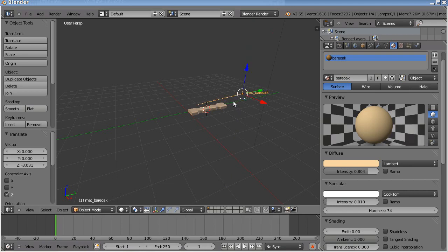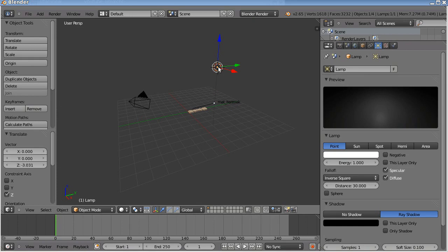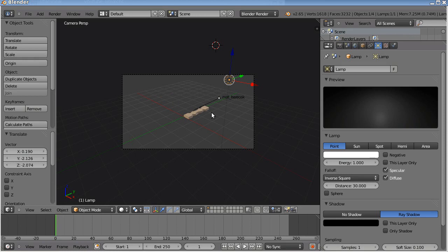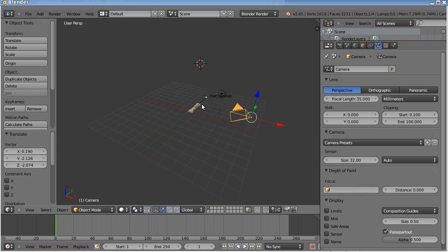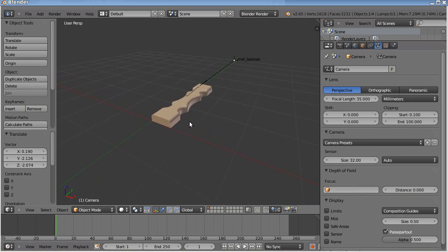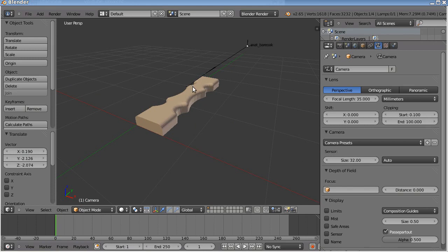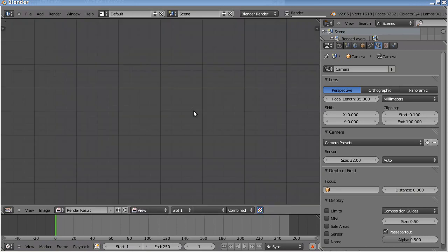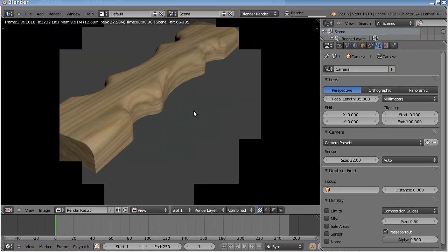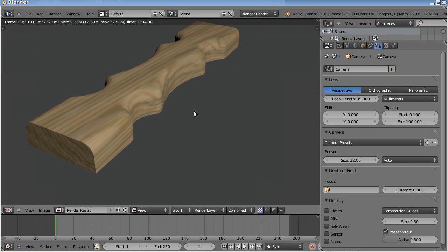Here do we have a light ball? Yes, we have a light ball. Grab it also down. Now move with 0 to see where the camera is. 7 is the top. I will move the camera a little more inside. I move in view, hit Control Alt 0, and we have the camera there where we would like it. And with F12 we will have a nice part, as you see here. This is basically how to do it.